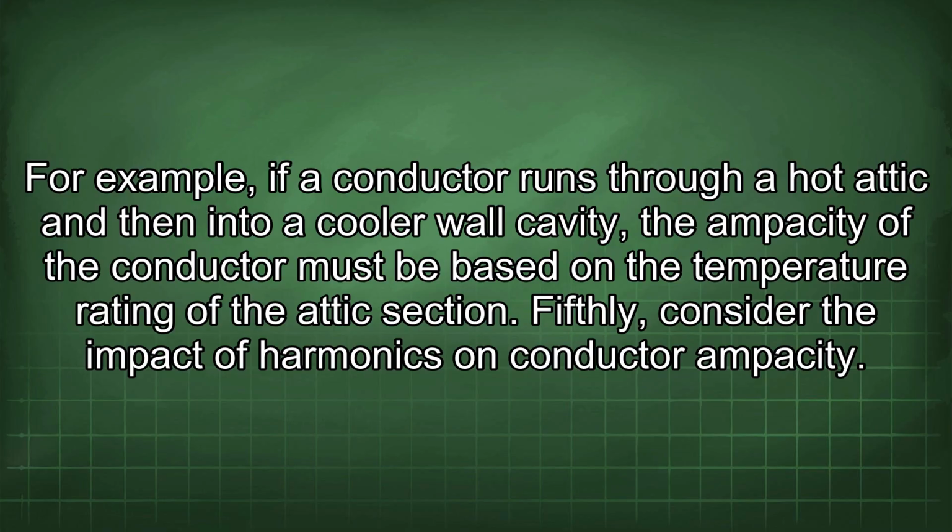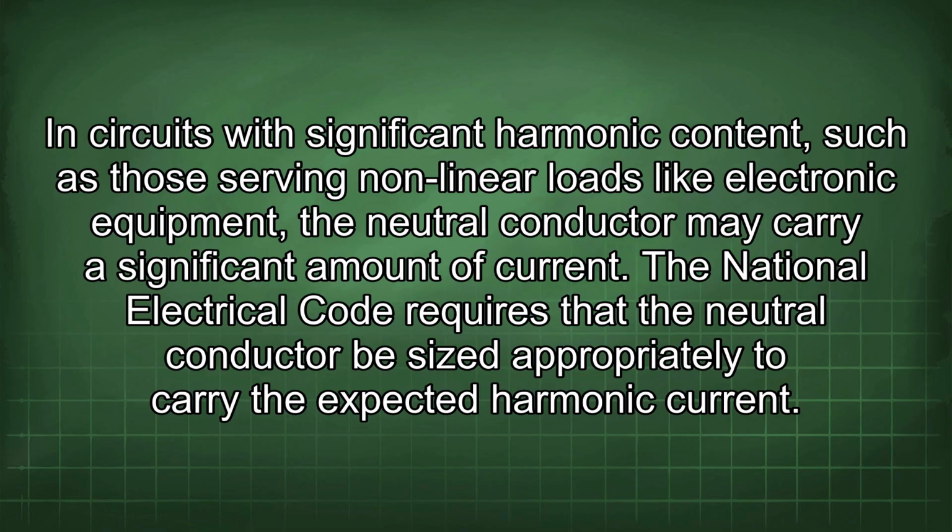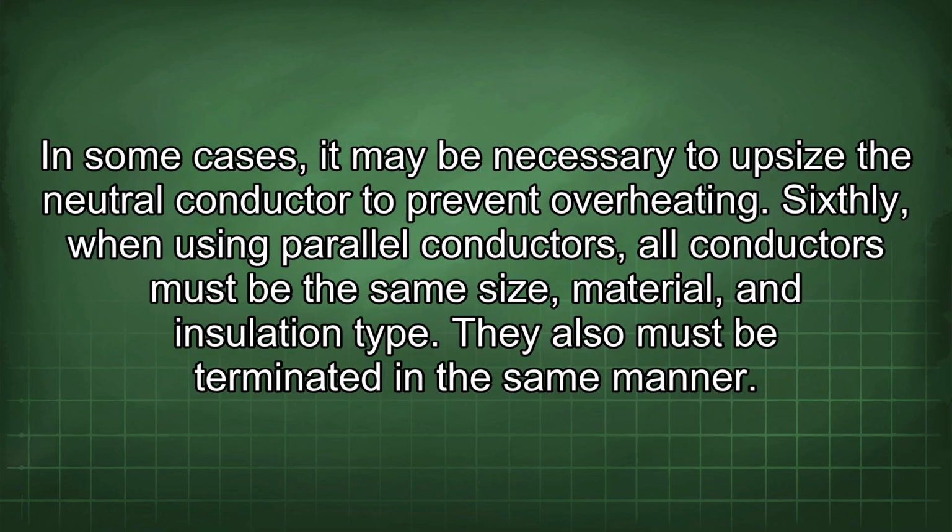Fifthly, consider the impact of harmonics on conductor ampacity. In circuits with significant harmonic content, such as those serving non-linear loads like electronic equipment, the neutral conductor may carry a significant amount of current. The National Electrical Code requires that the neutral conductor be sized appropriately to carry the expected harmonic current. In some cases, it may be necessary to upsize the neutral conductor to prevent overheating.